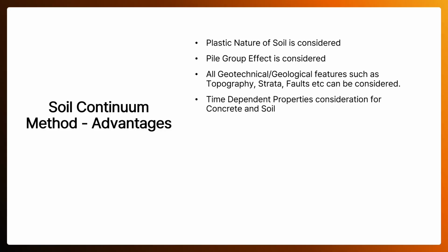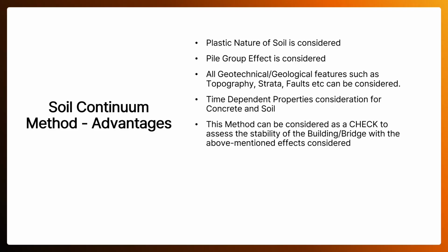The time-dependent properties like shrinkage and creep can be incorporated. And also, this allows us to check for safety and stability of the buildings directly in the geotechnical analysis tool. For example, you can bring the entire model from Civil to GTS NX, and you can model the surrounding ground. You can do a liquefaction analysis. You can model the water table, seepage. You can model excavations near the structures, and run different types of analysis like construction stage analysis or dynamic analysis, and you can check for the stability of the structure.